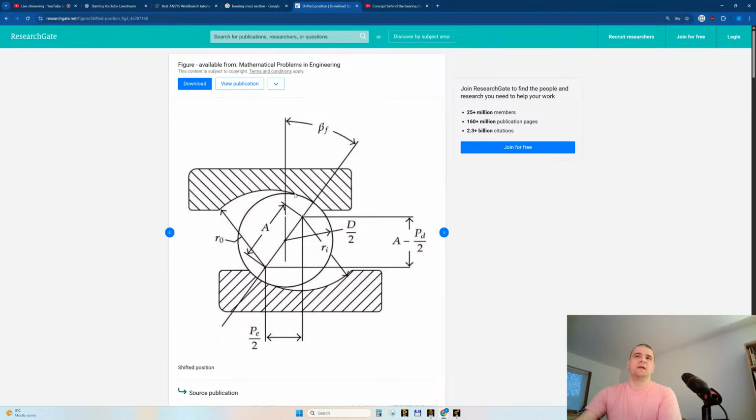All right. In reality, there will be lubricant, there will be less friction, because the purpose of the bearing is not to rotate the balls. Yes, we'll need to have as much friction as possible in reality. But for the purpose of the simulation, we'll need some friction in order to make it move from this portion and also this portion. At this moment, we will use the same friction coefficient, but maybe it will be better if we use a higher friction coefficient on one side. We will see.